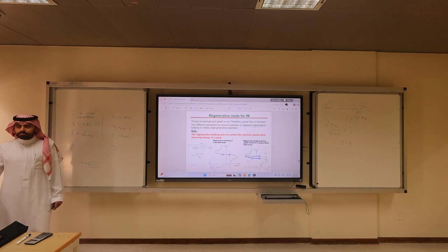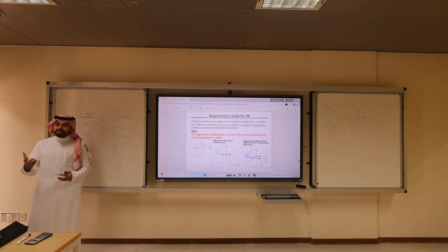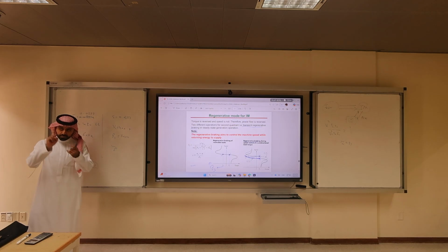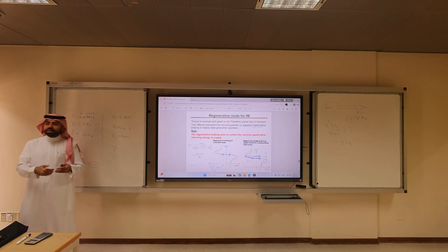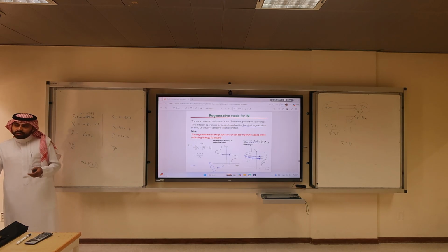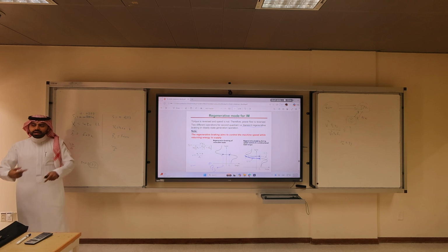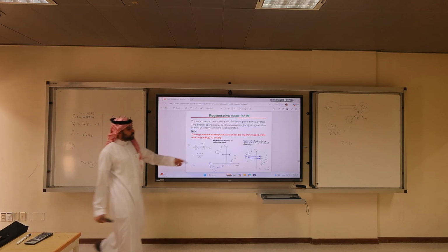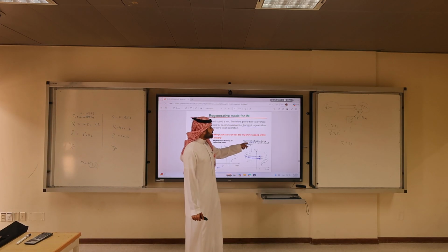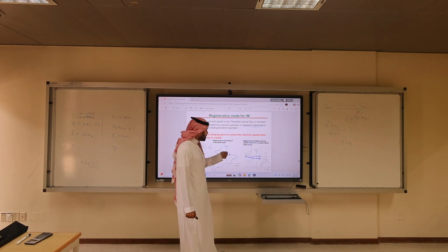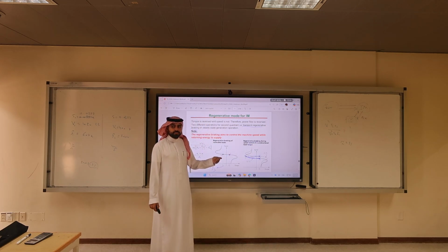What's the point of regenerative braking if you are connecting to the grid or giving back to the grid? Well, you're using the magnetic flux brake instead of mechanical. This is benefit 1. Benefit two, because of this electrical braking, you give back to the grid. Yeah, you save energy. Over time, it accumulates. Okay, clear? So when you apply V over F, you're gonna have regenerative braking during speed control. Remember, here you have speed control. Here you do not have speed control. You're maintaining the speed.